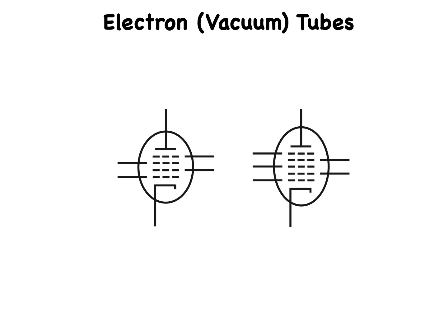The schematic symbol for a hexode is shown on the left, the symbol for a heptode is shown on the right. Some engineers called the heptode tube a pentagrid converter. Both of these symbols show devices with indirectly heated cathodes. You won't encounter hexodes and heptodes in modern electronics, but if you like to work with antique radios, you should get familiar with them. But take this warning, you'll probably have a difficult time finding a replacement component, should one of these relics go soft on you.